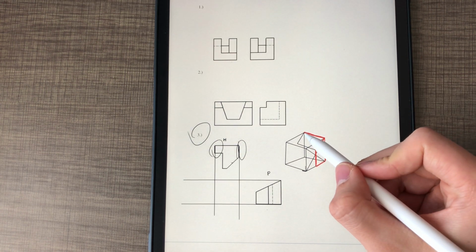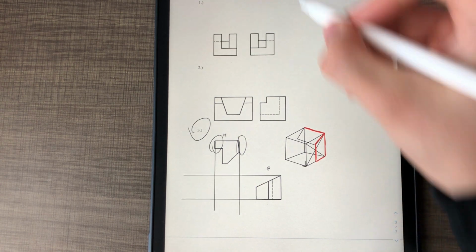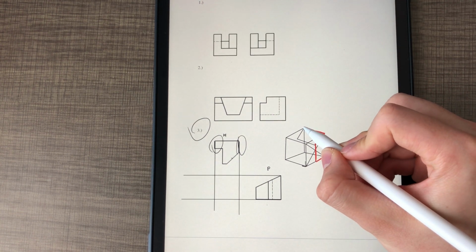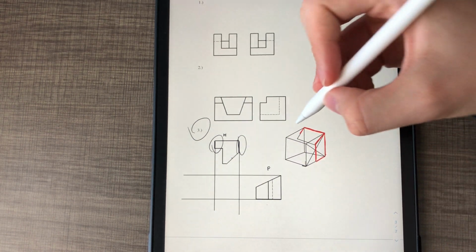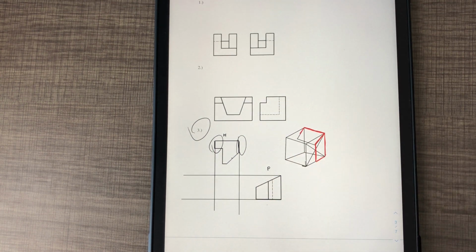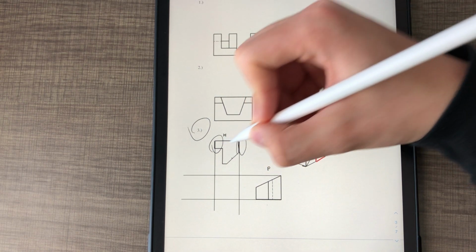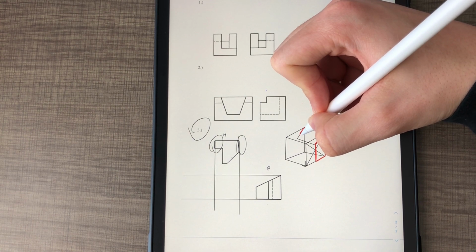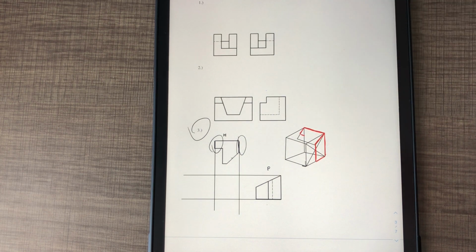over here is right up against the opposite wall that we were just looking at, right? So if I were to draw this down the same distance, so I would trammel this distance, I can now use this dimension and transfer it directly visibly onto my object. Do you guys see how that works? Okay, I can bring it in the same distance, parallel, you know, it's always along the same plane, and actually complete a part of this feature.